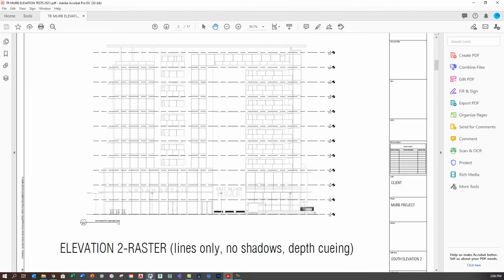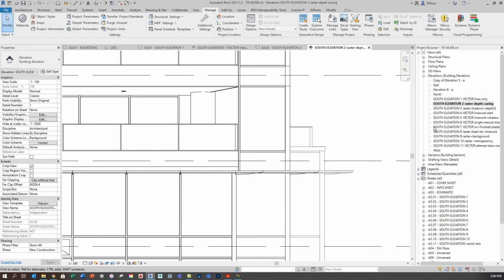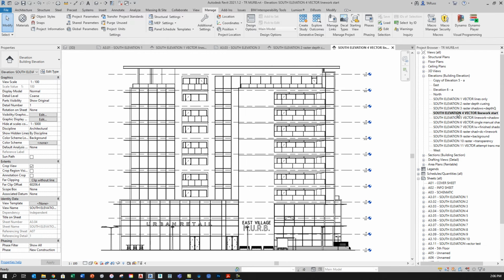I'm going to go back to Revit and start to play around with a different tool. This one's called the Linework Tool. So what I have here now, again, is the same consistent style. I'm using the hidden style, and in all of these views I'm just using the detail level set to coarse, in anticipation of creating the typical sort of look that we want with drafted views.